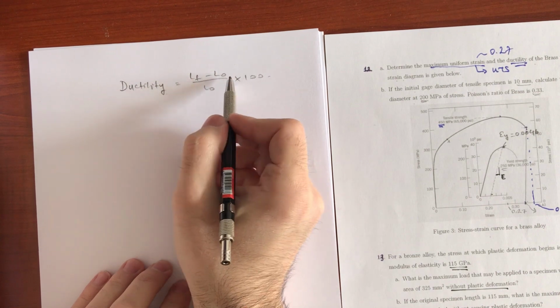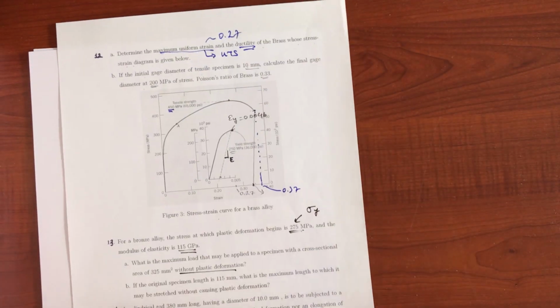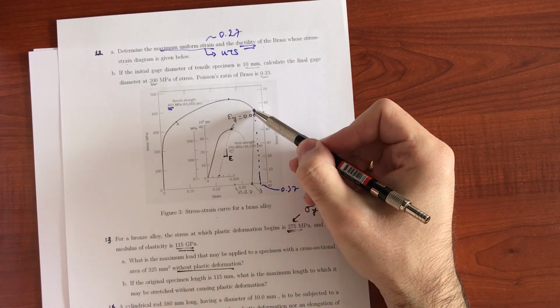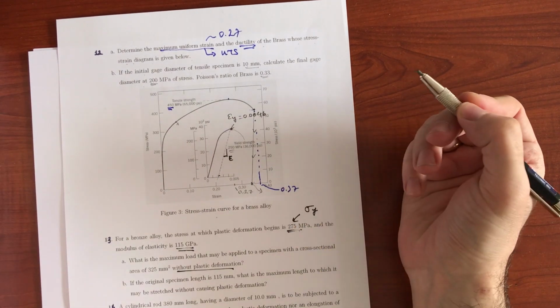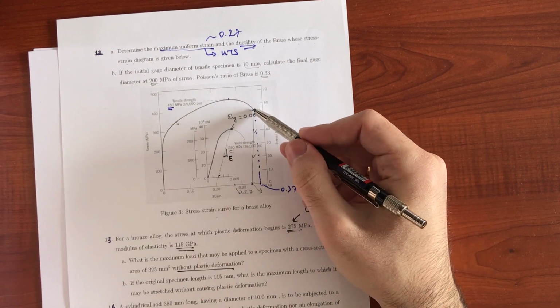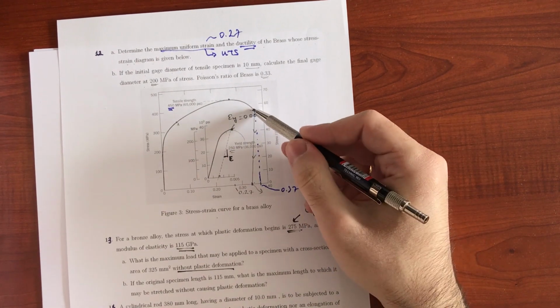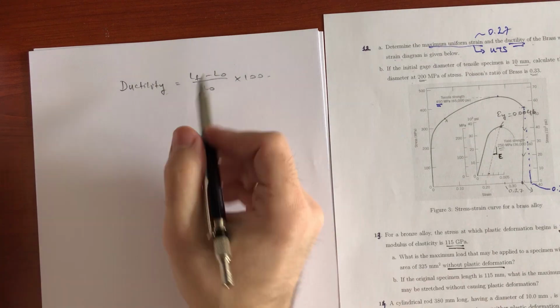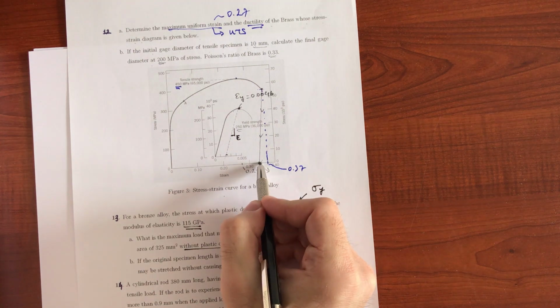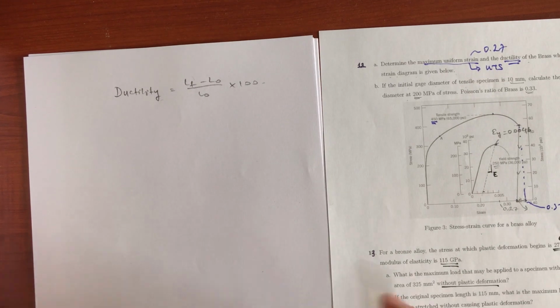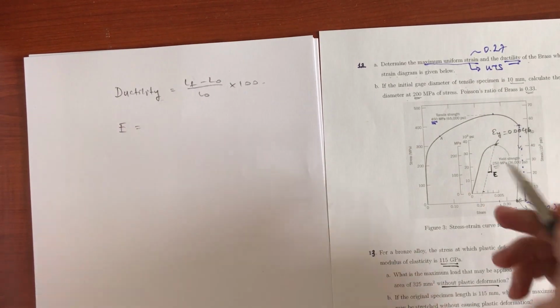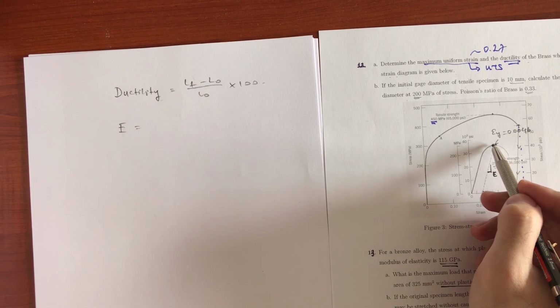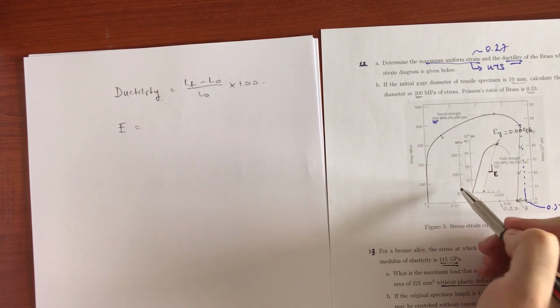Okay, now when we fracture the specimen, it will unload in such a manner. The unloading will be parallel to the elastic portion of the curve, and the strain at fracture will be different from the final length value that we measure. So in order to find this final length, we need to find the amount of elastic unloading here. In order to do that, we first calculate the Young's modulus, E, and we use the inset, the zoomed in portion of the curve.